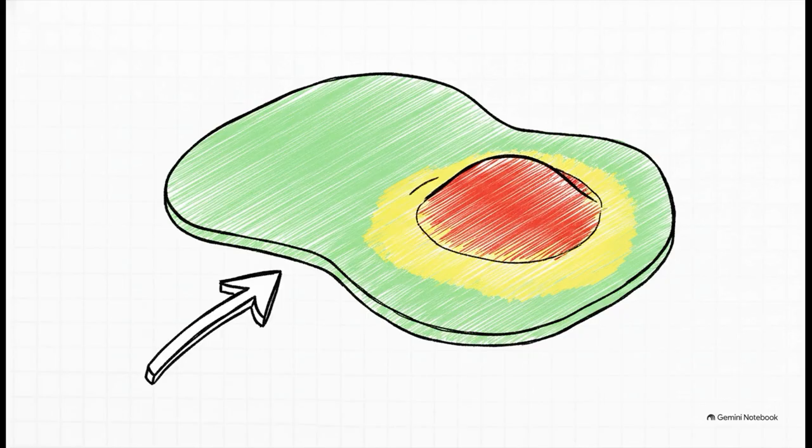What you get back is this incredible visual deviation map. Imagine a 3D model just glowing in greens, yellows, and reds. The hotspots on that map instantly reveal exactly where the tool deflected or where the material warped during the machining process. It makes it instantly visible if that tight lower segment requirement we just talked about was violated by a local high spot. You are literally inspecting a continuous surface with continuous data.